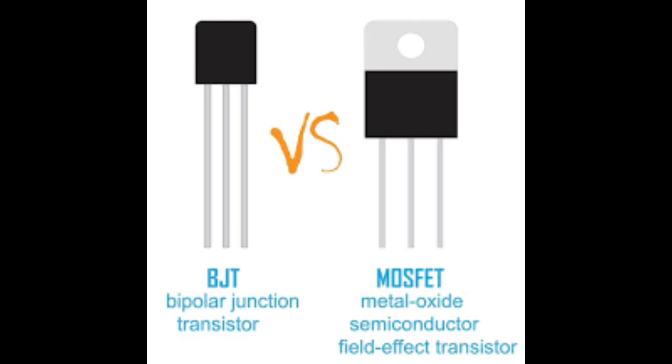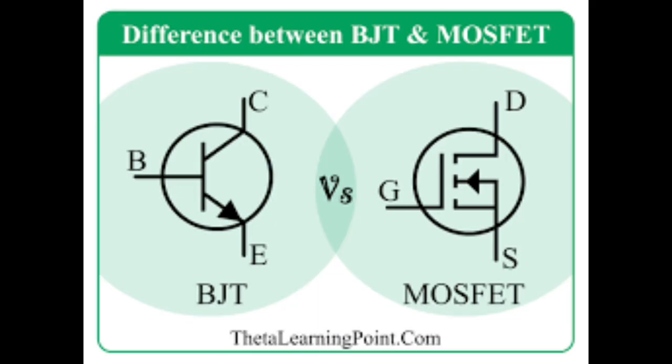The symbol for a PNP transistor has the arrow on the emitter pointing inwards, indicating current flow from emitter to collector. A multimeter in diode test mode can identify whether a transistor is NPN or PNP by testing the P-N junctions. The steps are: firstly, set the multimeter to diode mode. Secondly, identify the base. Test pairs of pins to find the base.